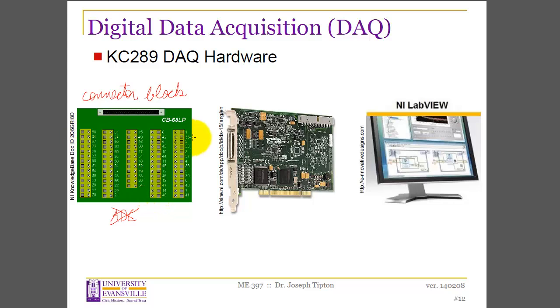card on the computer. So this then connects through a nice low noise connector panel into the DAC card. And this DAC card, or analog to digital converter, as we've seen in previous lecture, resides inside the computer in one of the PCI slots of the computer. Accordingly, its model number is the PCI 6221. And that's from National Instruments. That is the analog to digital converter system.